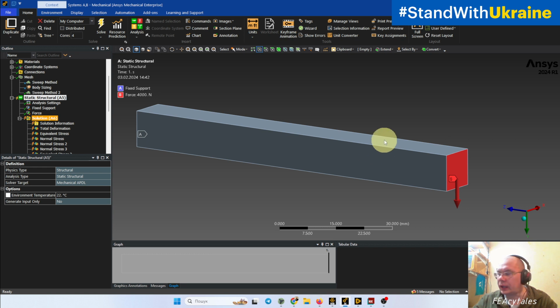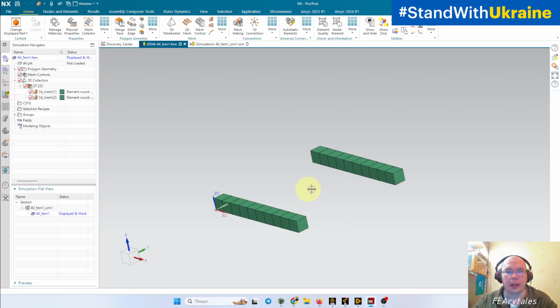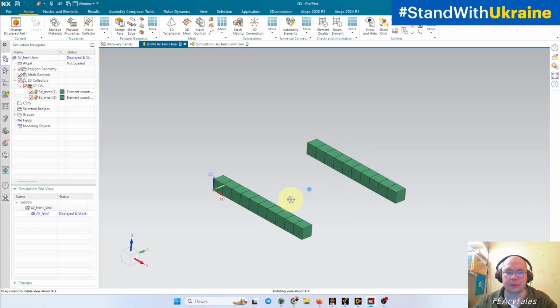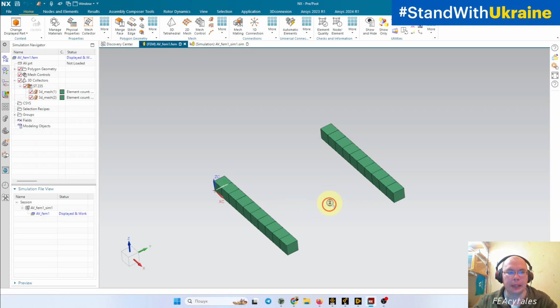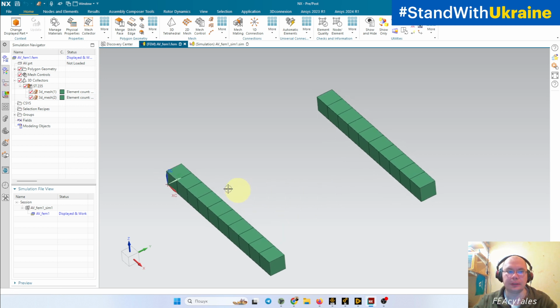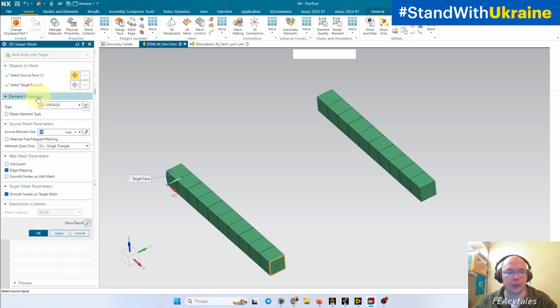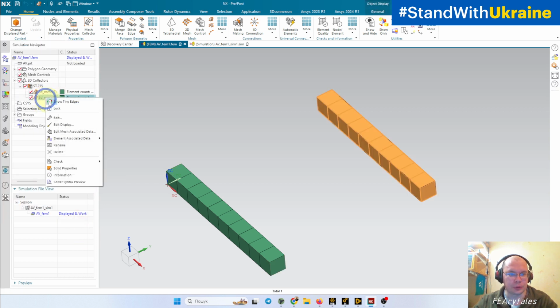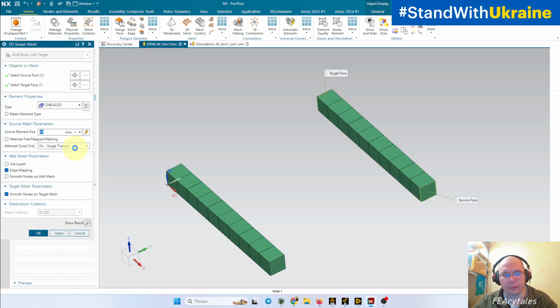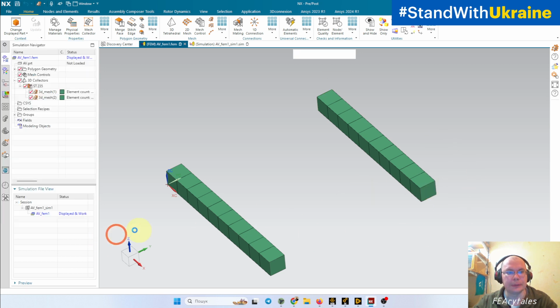And additionally, I checked this case with other software. It's Siemens NX Advanced Simulation, Siemens NX CAE. It uses NX Nastran to obtain results. And we have 2 different objects. One of them uses CHEXA 8 node. The second uses CHEXA 20 node, so it's a parabolic object.